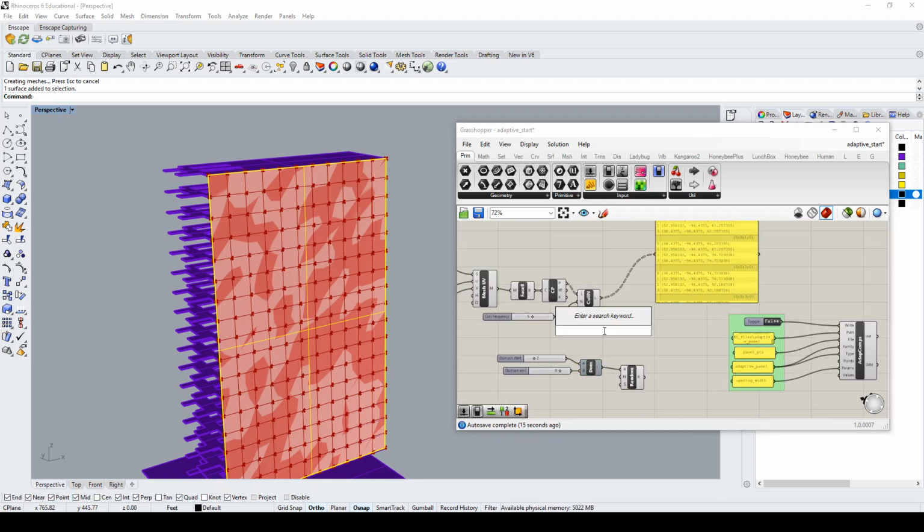So I can do that by doing the list length, so that if I end up changing my UV breakdown, this will automatically update. So this is telling me there's 187 panels, so that'll be the number of random numbers I'm creating.